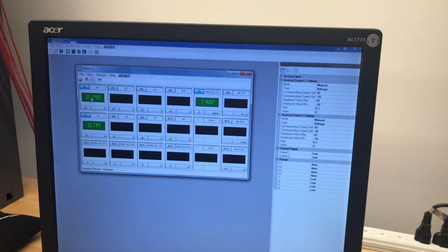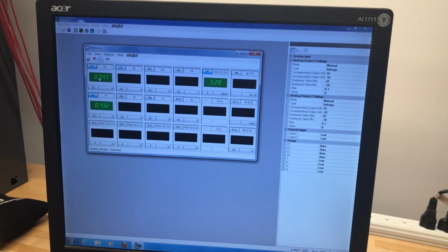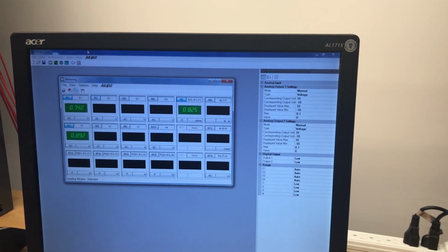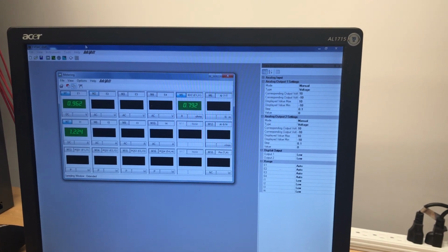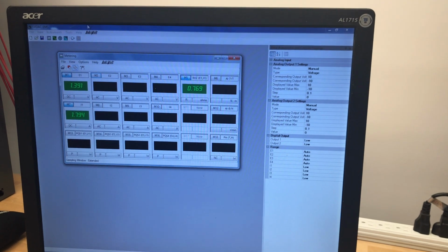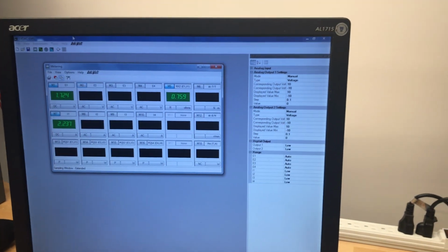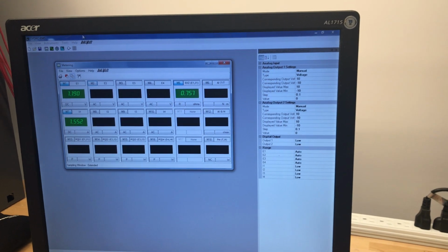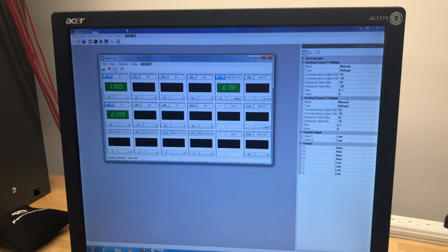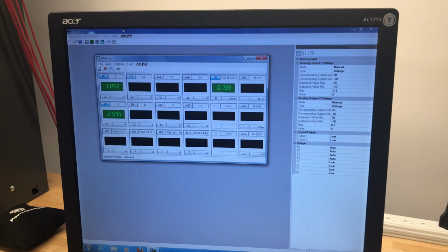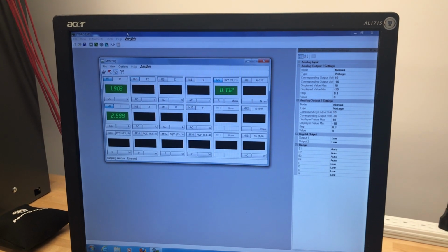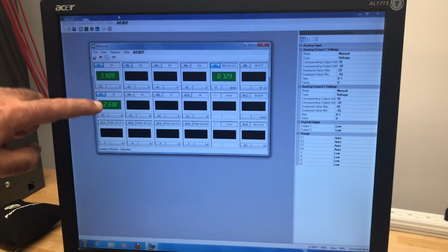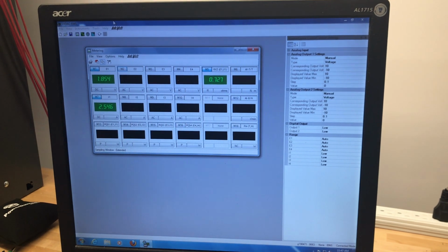Like for example, let me take the input voltage, whatever its value, it doesn't matter, any input value. So let us take, for example, as you are seeing the resistance here, this is the resistance. So let us make E1, for example, 1.896, and the corresponding current here, which is I1, 2.6. If you divide those, it will give you the value of the input resistance.